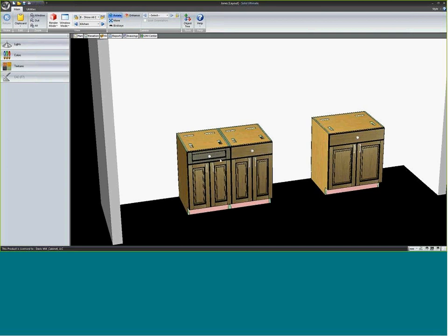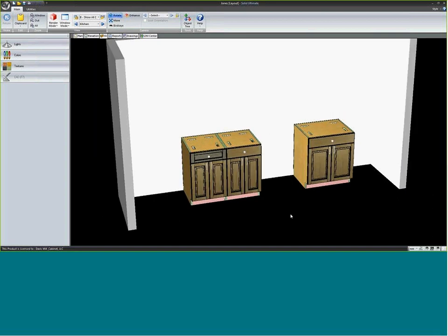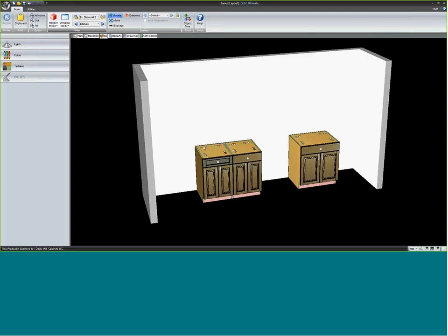We changed it to be a 5-piece front, but then later down the road, the client came back and revised the order and said, no, we want to change to walnut, not cherry. Well, this drawer front that I put an override on keeps its override. We've killed the intelligence of that item because it's a cabinet level or a drawer front level override. It maintains whatever we overrode it to, regardless of what happens in the higher up levels, the cabinet level or the room level.